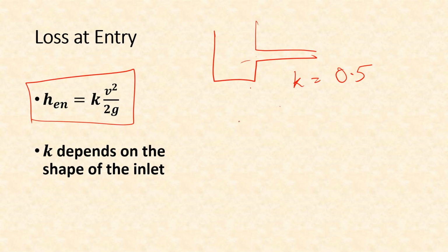But we can reduce this head loss by making a smooth entry or smooth transition. That is, if we make the transition like this, what we are doing is that we already know that the flow lines will converge, therefore we make the pipe boundaries or the entry to the pipe coincide almost with the streamlines, so that after contraction, whatever reduced cross-sectional area the flow acquires becomes equal to the actual area of the pipe.